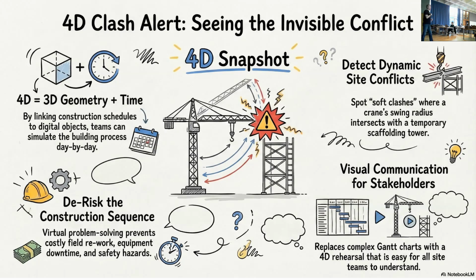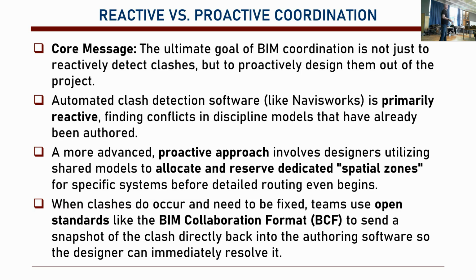So this is a bad location for the crane, probably. So we have to be clear about that, or we have to change the type of the crane. Or you need a space for moving materials, and in that case, you have a scaffolding and it's going to stop it. That's another clash. So these all change things.